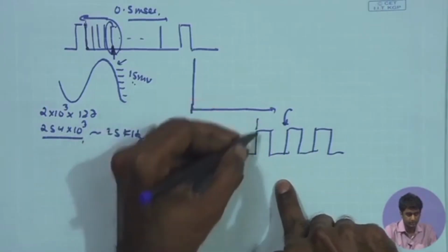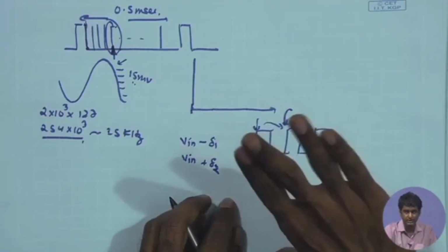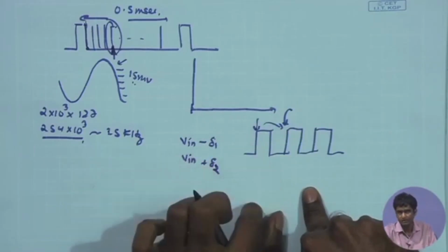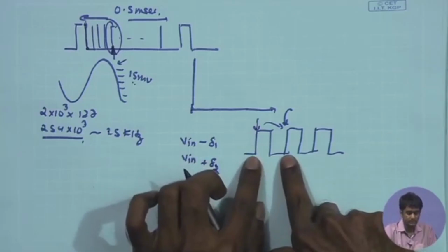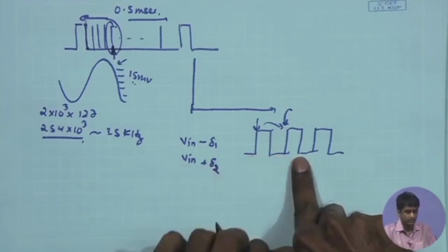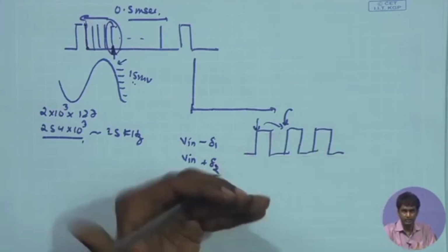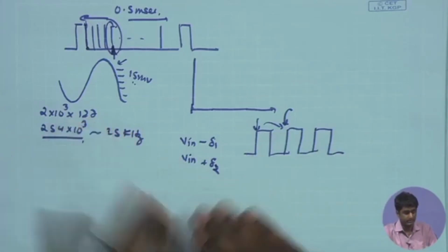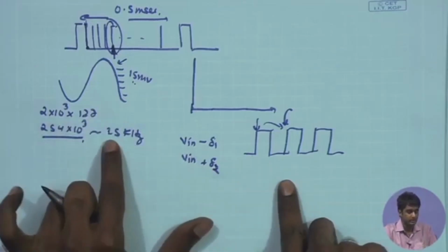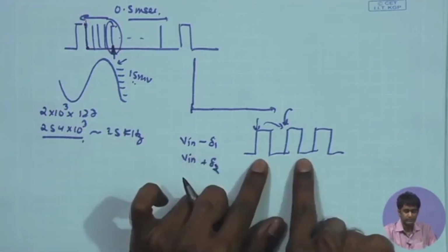So, from this particular rising edge to the next rising edge, the comparator should be able to change its output state and settle to the low value, and therefore, I would like to make sure that the settling time of the comparator is definitely lower than the period of the clock over here. So, here I would like to make sure that the settling time, which is given by the 3 dB cutoff frequency of the comparator or the amplifier which is being used as a comparator, I would like the 3 dB cutoff frequency to be sufficiently higher than the clock frequency that we are using over here.